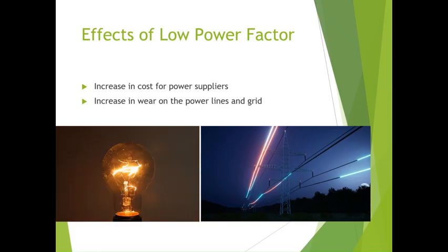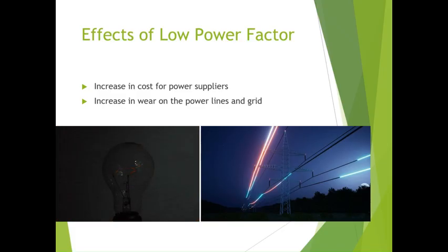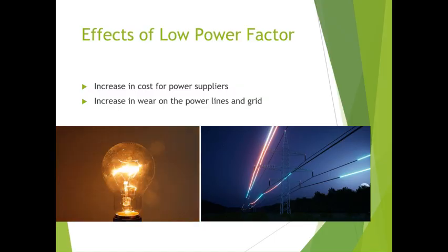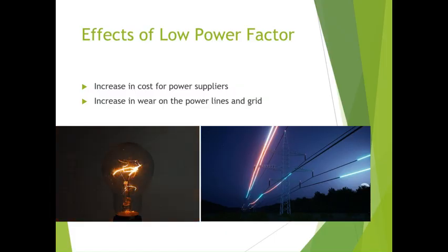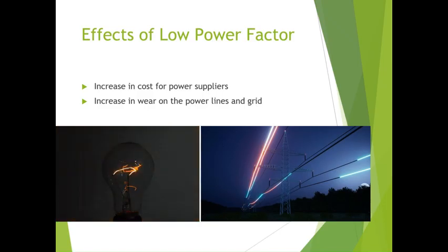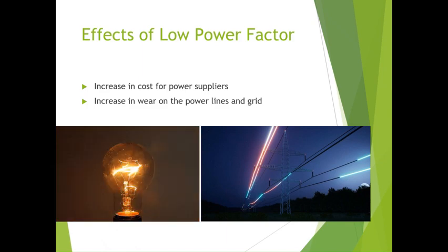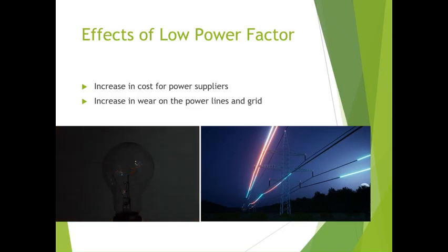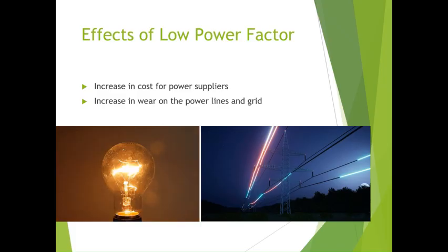A bad power factor can have negative effects. For example, a poor power factor can have a significant impact on the electrical grid's capacity. This is because a low power factor means more current has to be sent to deliver the same amount of useful power. This extra current being sent causes voltage drops, wasted energy, and overheating in the power lines. This causes negative effects for power supplies because they must handle more current to produce the same output.